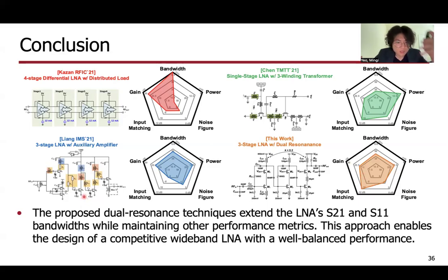So in conclusion, the proposed dual resonance techniques, such as the interstage magnetic coupling and the concurrent usage of resistive feedback technique and inductive degeneration technique, allowed us to extend the bandwidth of our LNA without critically sacrificing the other performance aspects of an LNA. So this approach enabled us to design a competitive wideband LNA with well-balanced performances.